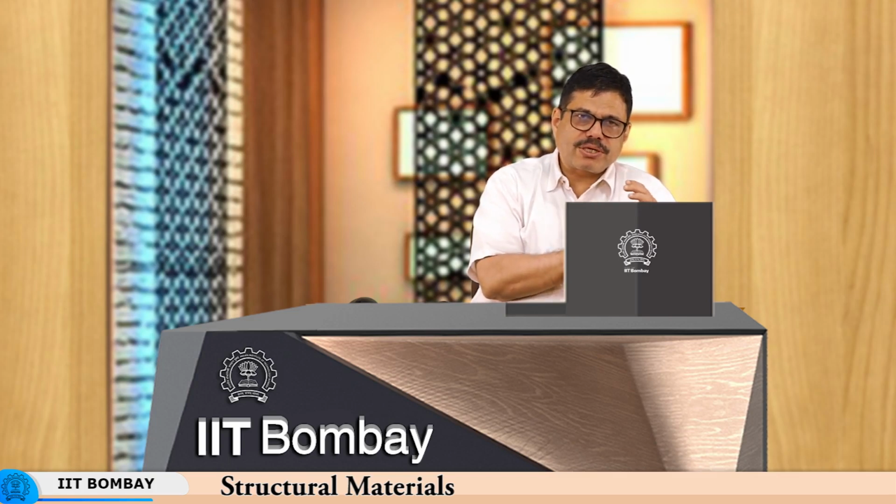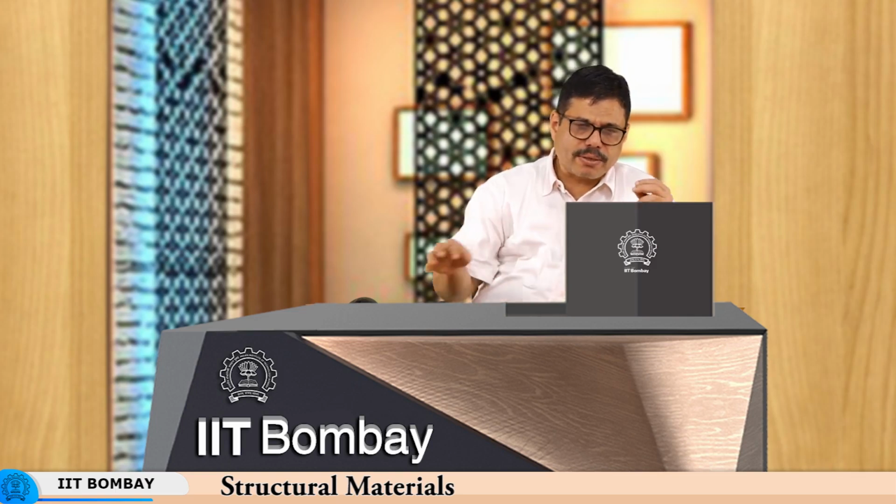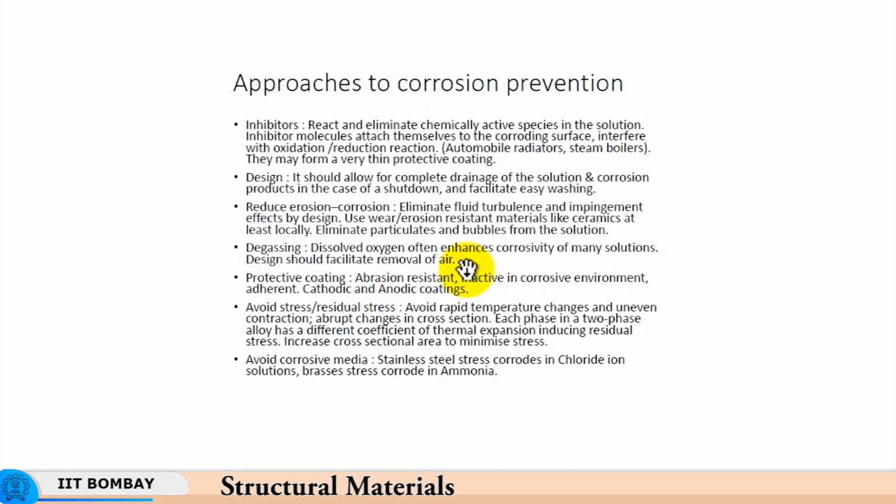Now, as long as both these reactions, reduction and oxidation, proceed in unison at the same rate, corrosion can happen efficiently. But if we add inhibitors that stop the oxidation reaction, then the corrosion gets stopped. Or if the reduction reaction is stopped, say you do not allow the electrons to reach the surface and combine with hydrogen, then there is a net accumulation of charge which on its own results in slowing down the